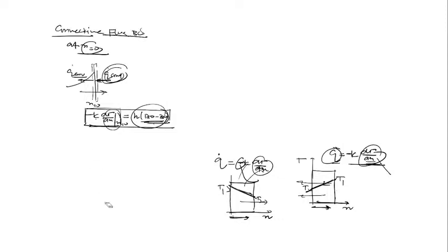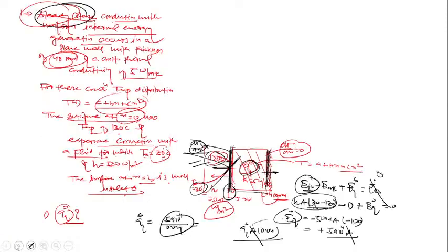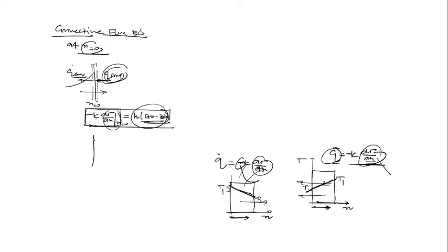So my suggestion is, in the case of convective heat flux, for example here at x equal to 0, I should write the balance in this way. Always write the interface boundary condition balance in the positive x. Let's say a surface is there, always write the balance like hA into T infinite minus Ts is equal to minus K into dt upon dx at x equal to 0. Then you will always get the correct value. Otherwise you will get some minus-sign mistakes. Clear? Area is not there because h is there. Now h is how much? 500.